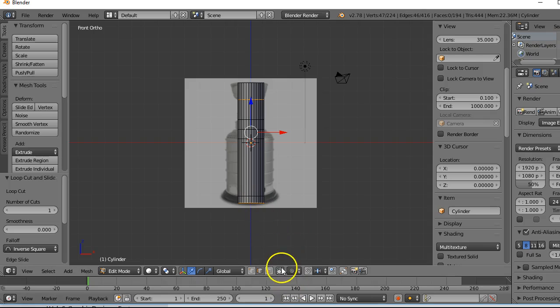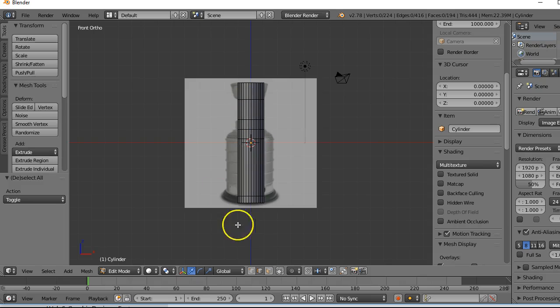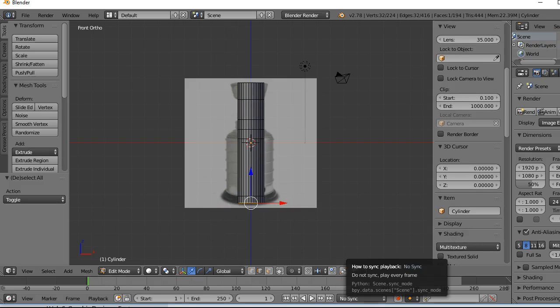Okay, so I'm going to activate where I can select. I'm not going to limit the selection to visible. I want to select all the way behind. I do want line select. I'm going to press B because I want to select that whole base bottom of line. So I'm going to press A because there's something goofy there. B, select. Should have those lines.